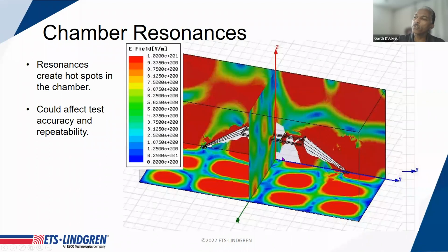This structure generates vertical E-fields between the radiating element and the floor of the chamber. And the plan was to position this over the aircraft being tested and radiate it at fairly low frequencies, down in the tens of kilohertz to tens of megahertz. And one of the things we did was look at how this structure would behave in the existing chamber that was built for higher frequency antenna measurements.